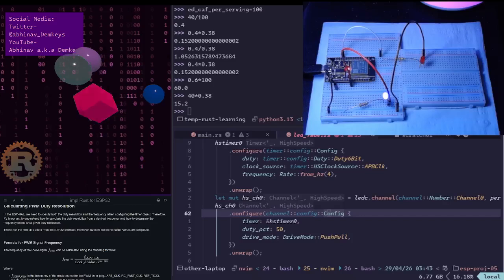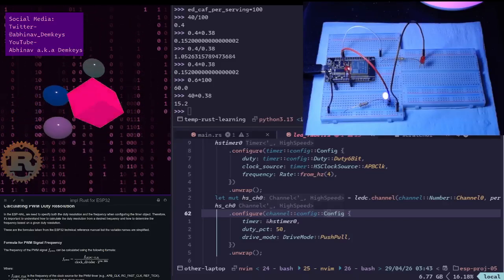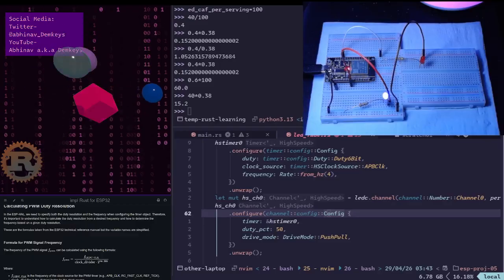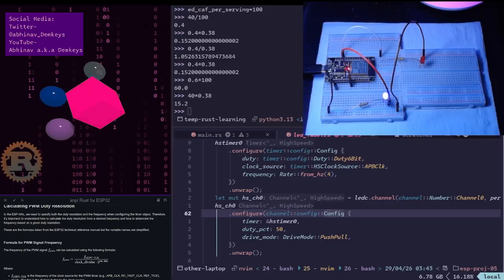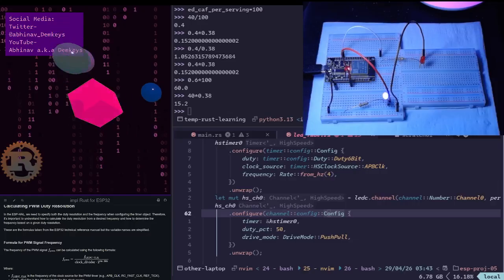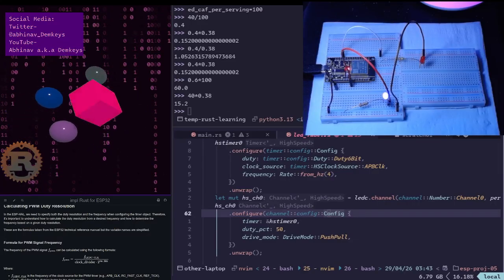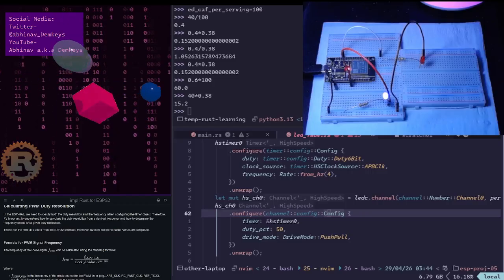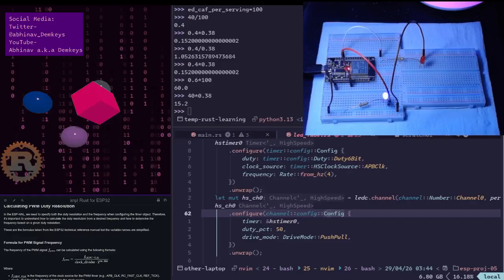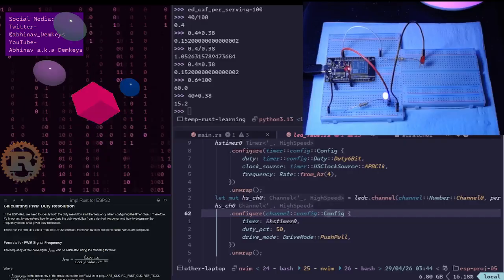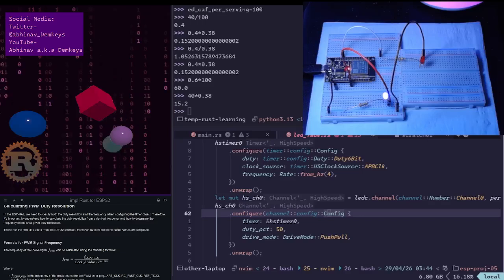And the other is if the divider that's being used to divide your higher frequency signal happens to be bigger than what can fit into the divider register, then also you'll run into an issue. And the reason I didn't realize that's what was happening was because I wasn't being given any errors. There's no errors being reported back. And so when I fed this into Gemini, Gemini explained that you have a 6-bit resolution,